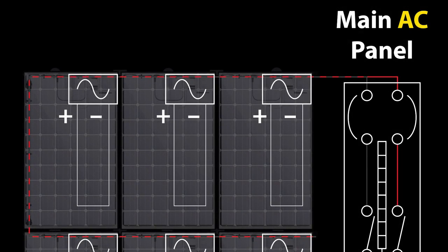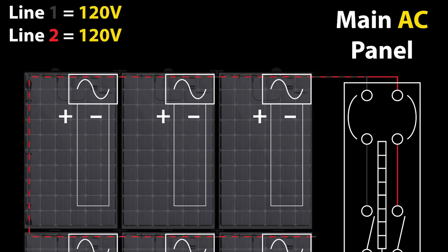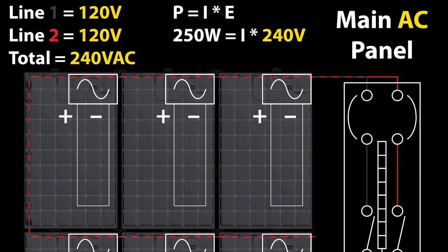The AC power supplied by the microinverter is based directly on DC side production performance. On the AC side of the circuit, the microinverter detects and supplies a voltage consistent with the mains electrical system at the customer premise. That is, the AC voltage across line 1 and line 2 conductors. In 3-wire split-phase systems like the United States, the voltage across the hot conductors is 240 volts. So for a 250-watt microinverter to produce peak power, it must output AC power at approximately 1.05 amps.